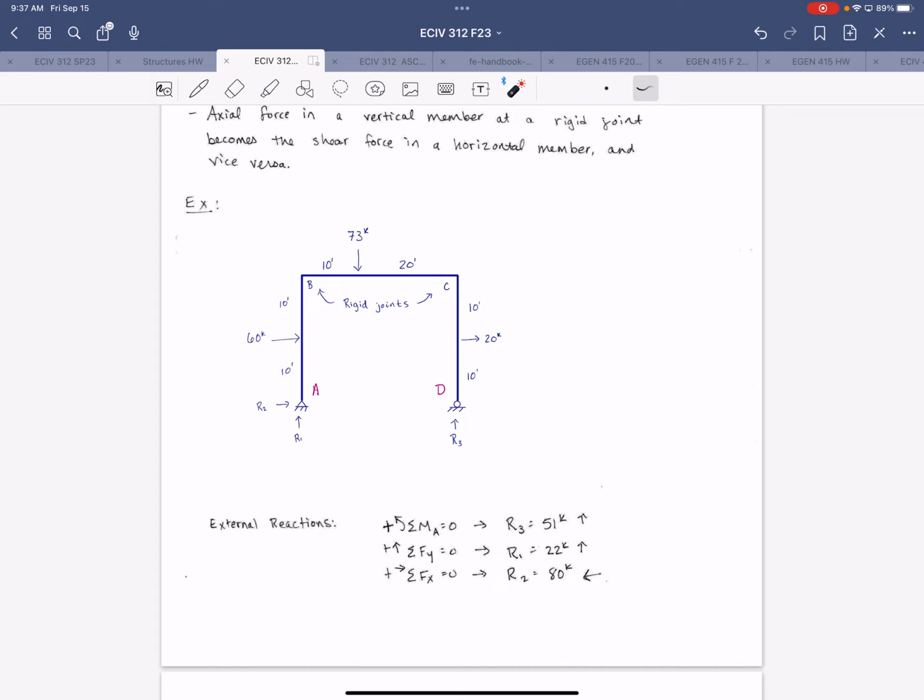So sometimes with trusses, or I guess more often with trusses, you can get away with not finding the reactions first before you find internal forces. But with frames, that's much less common. An example of being able to do that might be if you had a cantilever extension on this side maybe, and some load on here, you could break that off, because you have a free end here. You could break that off and have 3 unknowns at the rigid joint, and you could solve for the forces at that joint before you get any reaction forces. But for a frame like this, you have to find the reaction forces first.